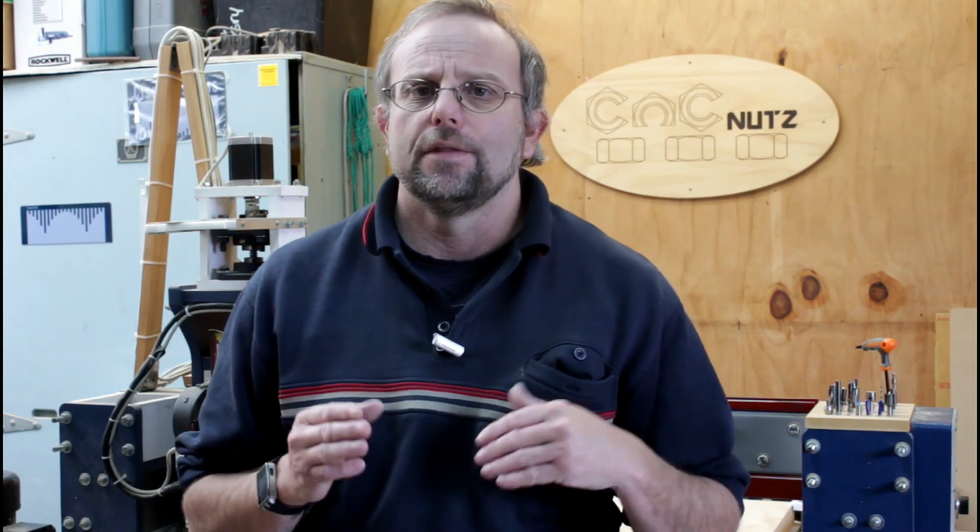So how does any of this help us? Well, what we've actually done is two things. First of all, we've set our cutter to the surface of the material, and that's going to be great. That means our pockets will actually cut to the depth that we specify in our CAM software, in my case 4mm. But the second thing we've done is we've managed to calculate an accurate offset to work out exactly where the tabletop is once we're ready to do the final profile cut.